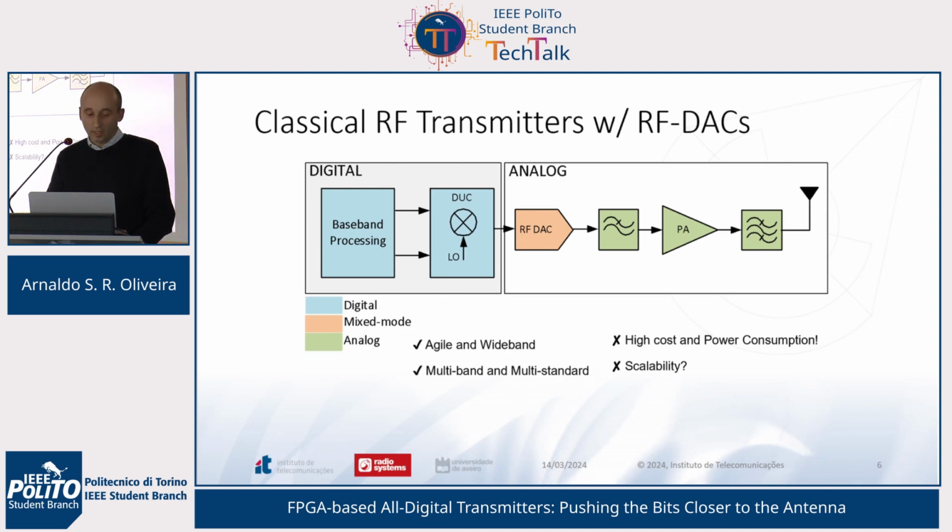This architecture has the advantage of being more agile, wideband, and also supports naturally multi-band and multi-standard capabilities because these features can be handled efficiently in the digital domain. However, they are still high cost. Some solutions start to appear, but they are still high cost. The power consumption of high sampling rate DACs is considerable, and scalability is also something that needs to be proved.